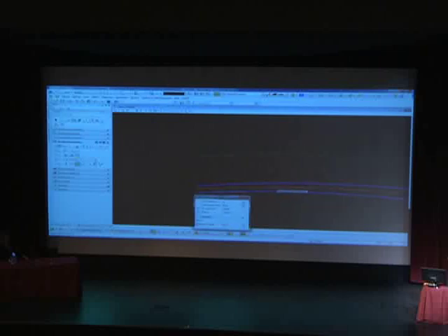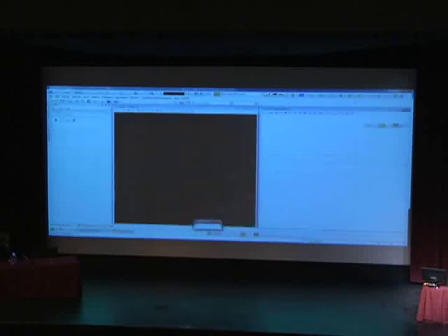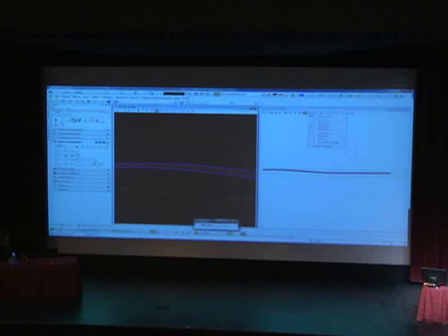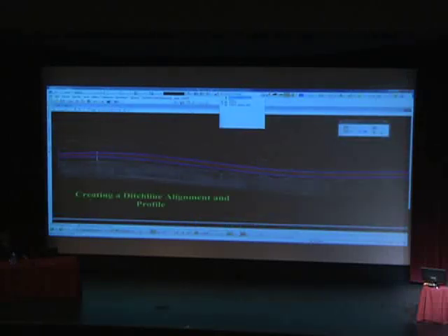Well, with the 3D model, you could easily reference in that edge of pavement to, let's say, your ditch line. Let's say you want to stay 2 feet below your edge of pavement, right? That's the upper bound for your ditch line, or you don't even want to be there. So you could easily reference that in and see it in multiple views. And also, if you have an intersection that you need to tie into, the intersection could tie into that edge of pavement, and it's just overall good to give it a Z value. What I did here was I just did a right-click view 2D, 3D, and so the 3D view actually pops up on the right-hand side here, and that's actually the 3D model space, so treat it as a separate DGN.